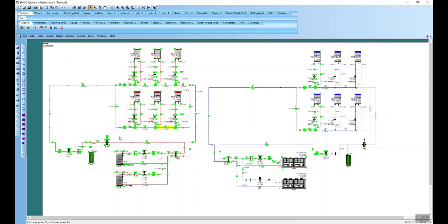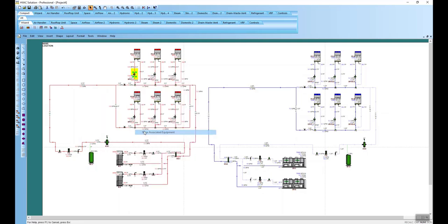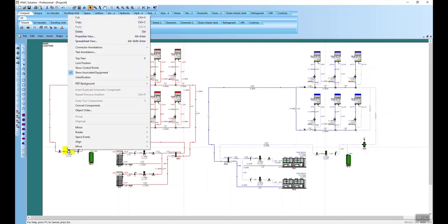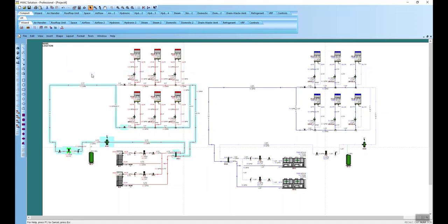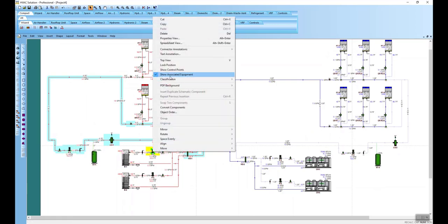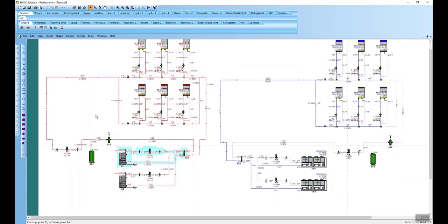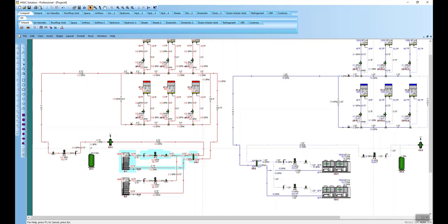all that information. A few other things, since it's a primary secondary system with a single pipe, there is the associated pressure drop of that loop. Here's the pump down here with my pressure drop loop path. That's what makes up that head of 18 feet. And then the primary pump's down here, right there. So a few things I need to do to